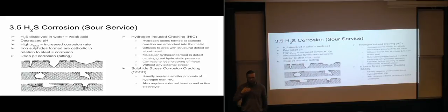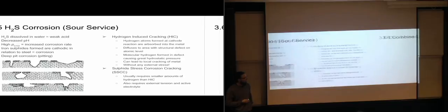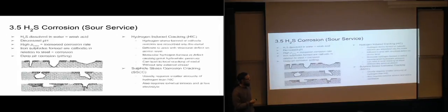But the hydrogen-induced cracking doesn't need any external stress in order to happen, while the sulfide stress corrosion cracking requires tension from an external source, and it also requires an active electrolyte in order to create cracks, basically.